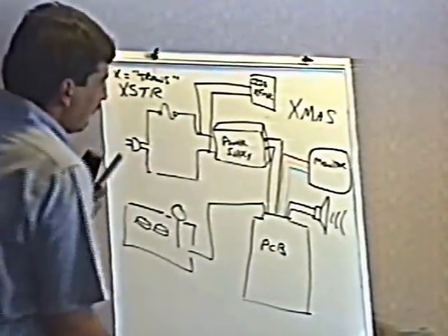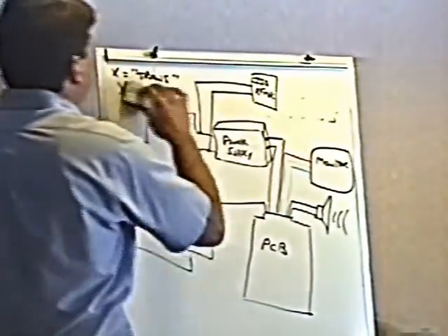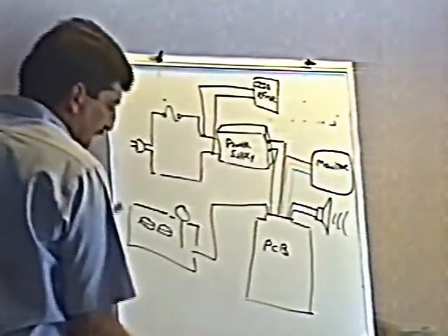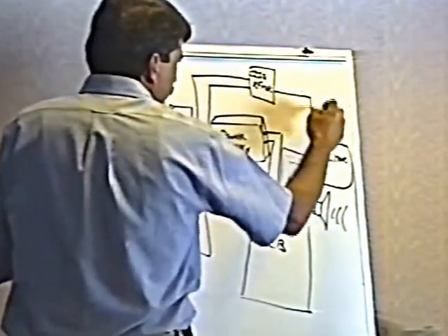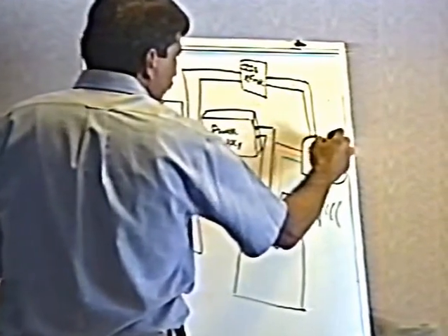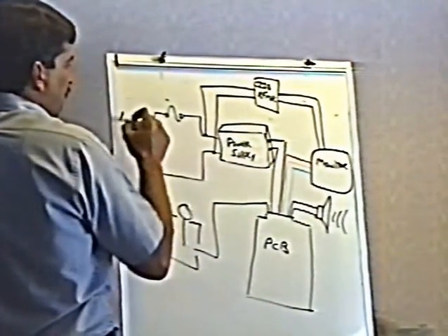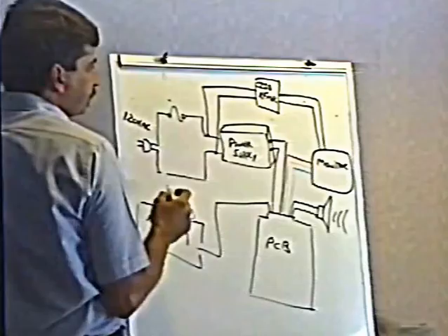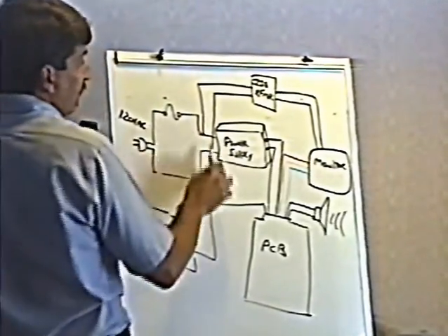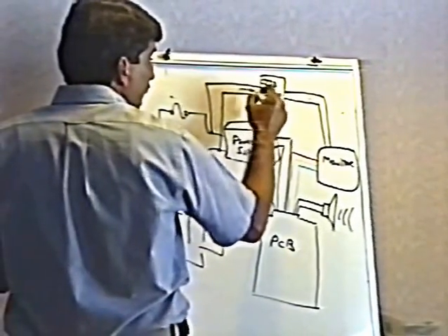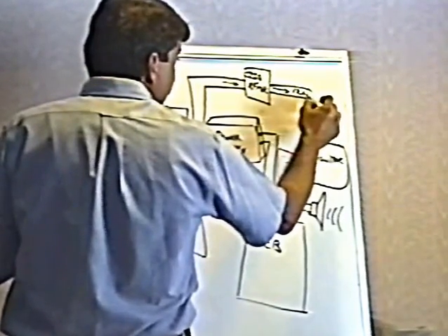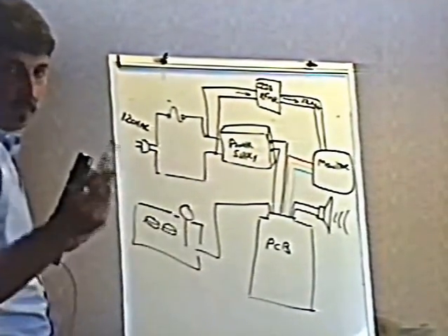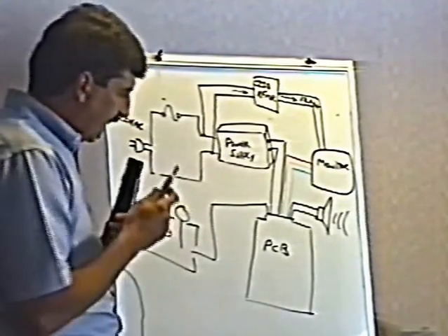So anyway, the isolation transformer is not something that never ever fails, really. The isolation transformer is then used to power the monitor. And of course, this is the 120 volts AC. The isolation transformer takes 120 volts AC in and gives you the exact same thing out, but it is isolated. It's a safety transformer. I mentioned it to you before. I'll cover it again in just a little bit.